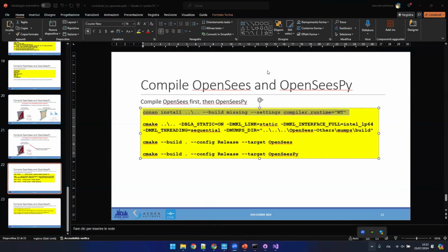There is a question, once the C++ framework is done, how to include it into OpenSees? I will show it to you right now. Then the second question, the way you show here is for building a material model. How if we wanted to build a new element? It is very similar actually, because as I created a new material that is derived from uniaxial material, you can create a new element which is derived from element. The concept is the same.